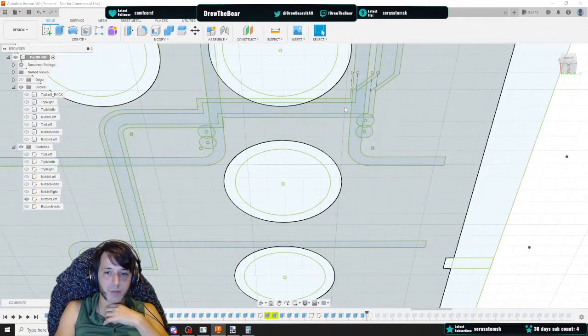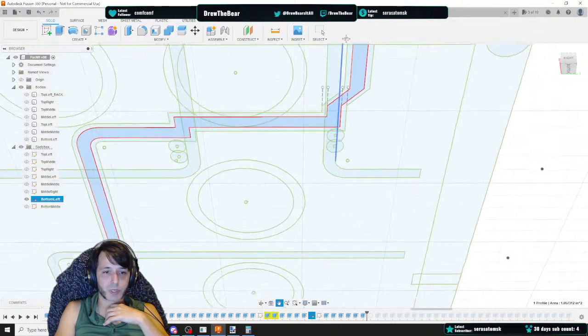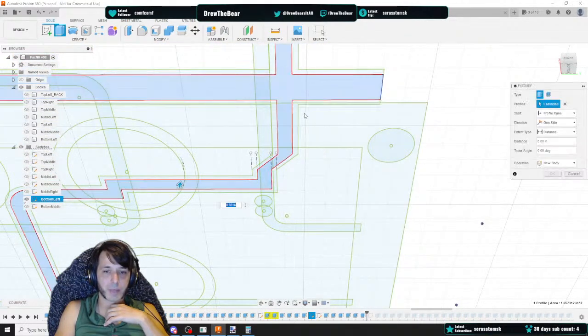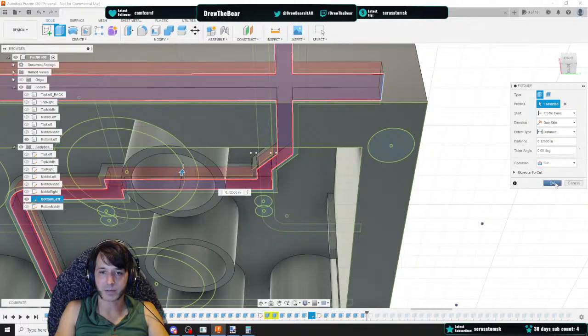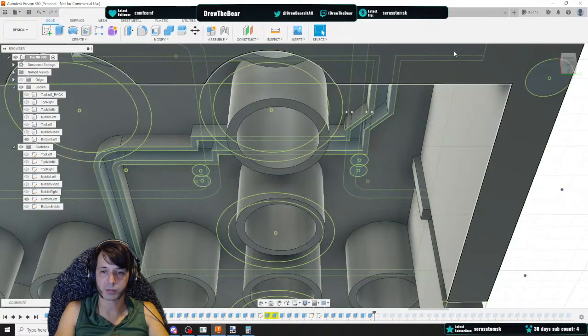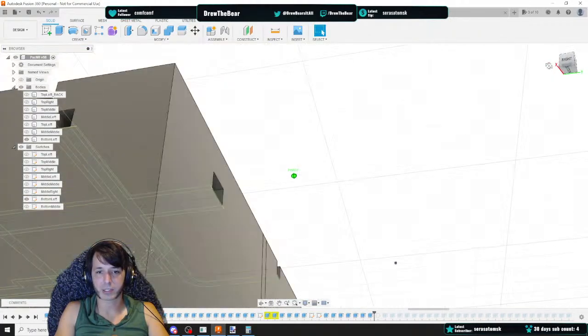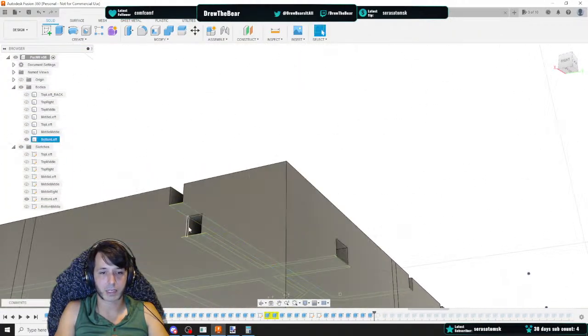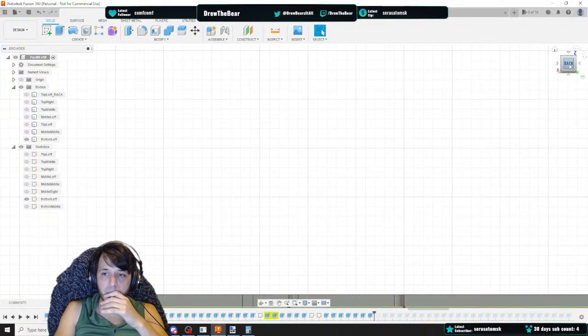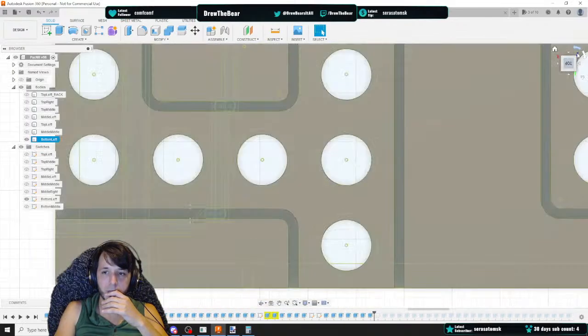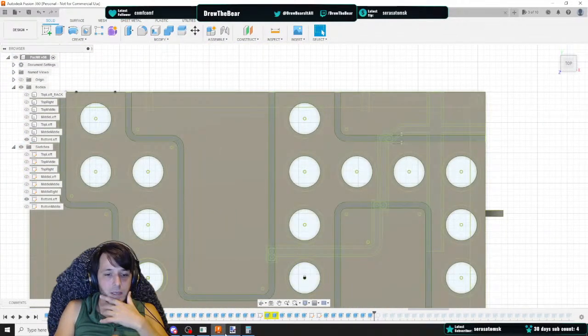Now, grab that center point, and we're going to make sure, it might not even detect that they line up or touch in any way. We're going to do this to 0.125 and cut. And that'll make sure that there's holes through the walls. So as you can see, what that just did is it created a hole here and here, so that we can push wires through between the two blocks, pieces of the 9 pieces. Okay, so top here.